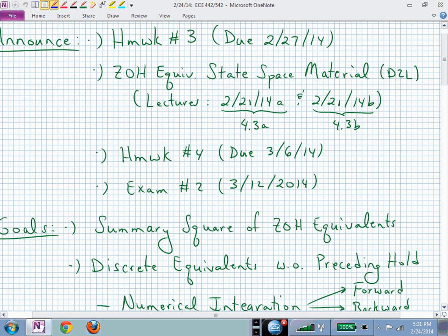And actually in the B part, I try to develop some equations of motion for a mass spring damper system. So we're going away from ECE in that particular second order system, draw or sketch the all-integrator block diagram. That immediately gives us our state space representation in continuous time, and then we proceed to finding numerically what that second order, zero order Hold equivalent discrete time system looks like.